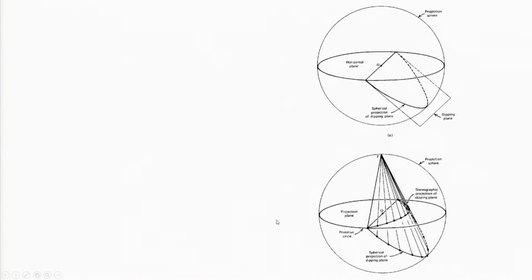And if you want to determine the stereographic projection of this inclined plane, each face pole that lies on this curvature, you can now join with the north pole here, that has been done here. So, it is intersecting this horizontal equatorial circle, which is the horizontal plane, and these are the intersection points.